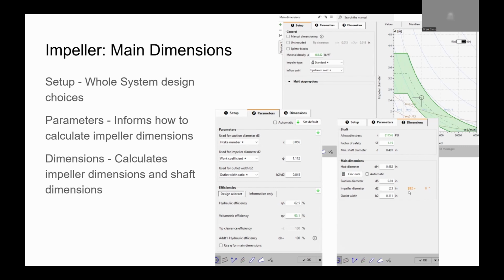As you can see, there's the beta angle calculation that goes along with this diameter, and it's 0 degrees right now, which is throwing an error. That is something that we'll obviously need to change because CF Turbo is coming up with some math that doesn't make sense. So sometimes I'll mess around with this diameter to allow for better blade angles, and then we can work on the blade angles to reduce turbulence.